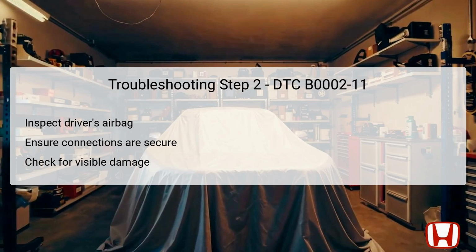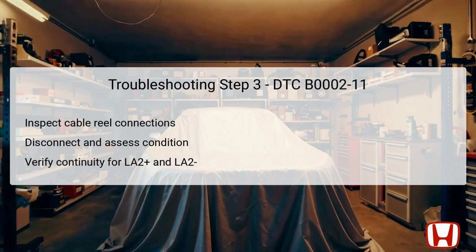However, if everything appears normal, yet the code persists, it suggests further scrutiny of associated components like the cable reel or SRS unit might be necessary. The next step in the troubleshooting process is to inspect the cable reel connections.